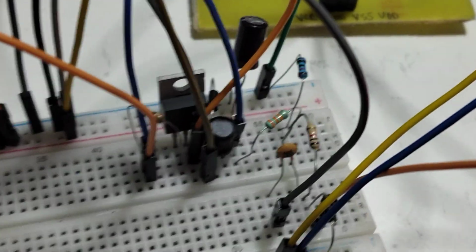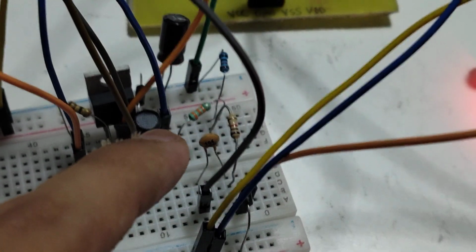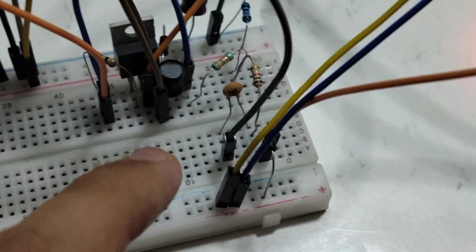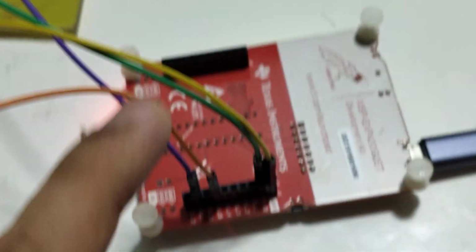So yeah, just to mention, I forgot to show it before. This is the voltage divider. We have the 33k and 10k there, and that's the low pass filter, 1k and 100 nanofarad. And yeah, this orange wire is basically how it's going back and reading it from the ADC.